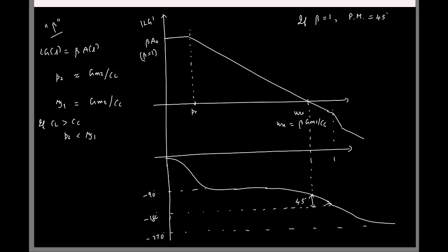As we saw in the last class, a phase margin of 45 degrees will result in peaking in the closed loop frequency response. So what is the usual phase margin you want? Greater than 60. 76 degrees if you are great, but at least 60 degrees we need.